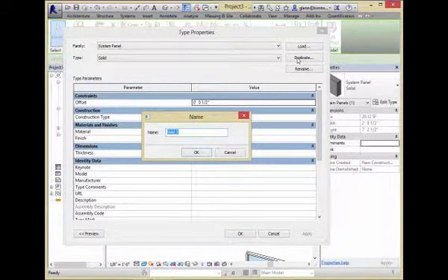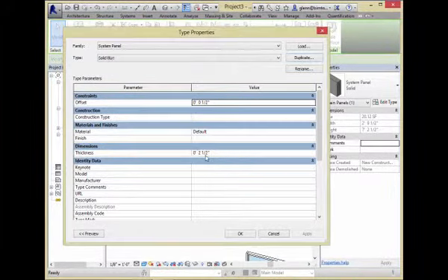I'm going to go through and make a nice solid blue panel. This is the definition right now. Notice it still has the default type, because that's just a textual description of it. If I want to change that material, here's what I do. I go to that default material, and materials are chosen, as opposed to typing in values, in this thing called the materials browser. How we get there is that little dot, dot, dot right there.